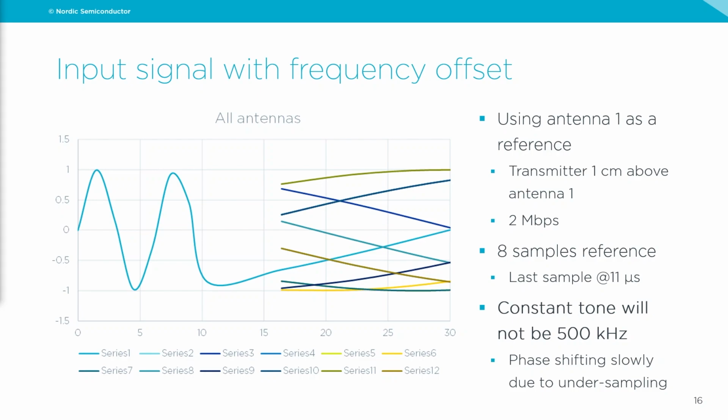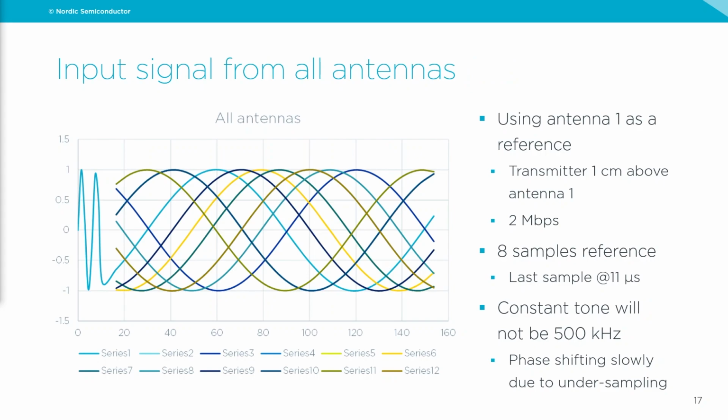So again, one of the reasons why we say that this is a little bit tricky is how you do the visualization of the data. In a lot of cases, trying to do a visualization of this data will just make it worse. Same if you start looking at a longer period, it will look like there are sine waves again, but with a lower frequency than the blue one, and the frequency of these will actually be the mismatch between the transmitter carrier frequency and the receiver carrier frequency, as well as the modulation index, because this one is modulated as analog voltage, or as an analog based frequency.